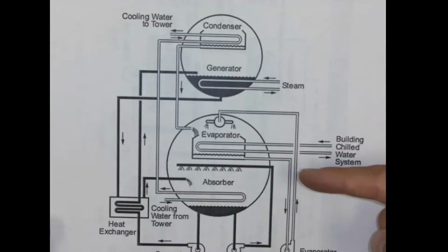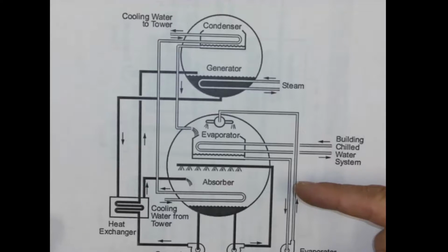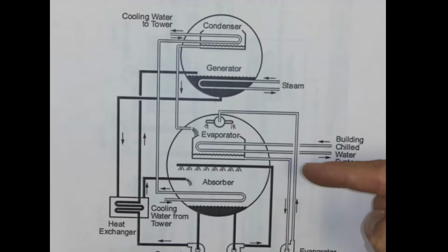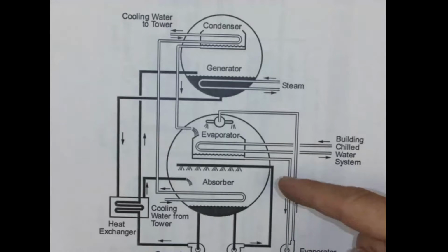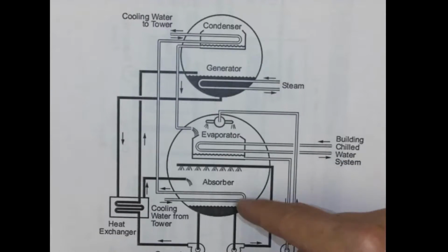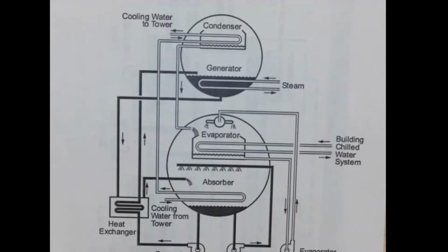And the reason for that is often we have very low pressures in our systems, so we create one significantly sized pressure vessel which can hold the low pressures, as opposed to a whole bunch of different components in other vessels. So that's one reason why we've gone with this route.